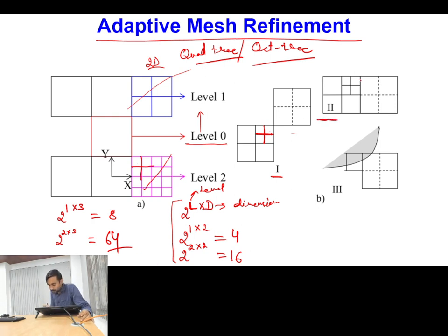So in arrangement number 2, exact aligned neighboring cells also cannot have a level jump more than 1. So here you can see this jump, so I have to create this dashed line because I cannot have a jump more than 1. Okay, so similarly, if this is my interface, and when I am creating this quad tree mesh, it will not happen that in one cell I have the interface with fine arrangement and in the other cell I have the interface in a very coarse cell.